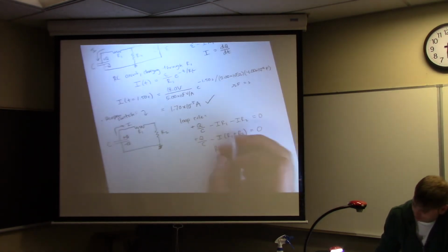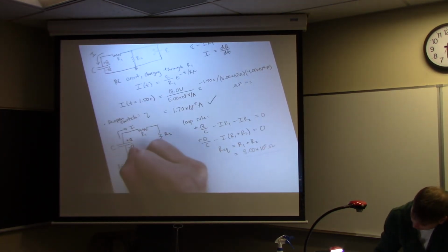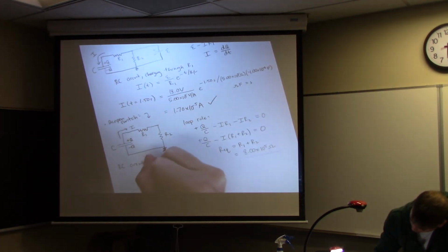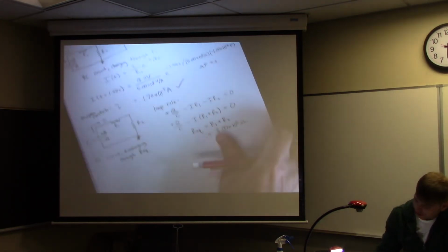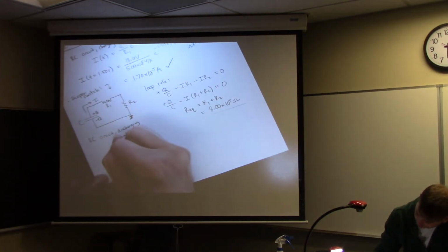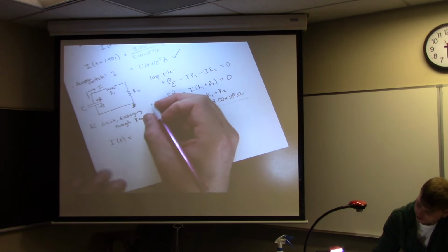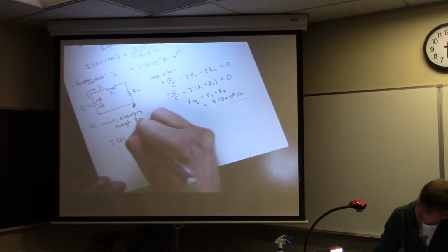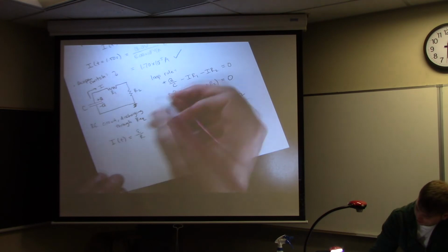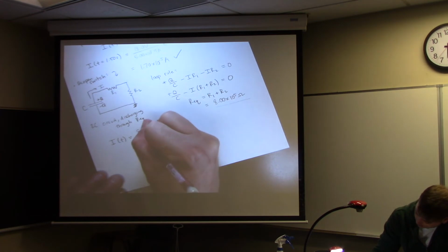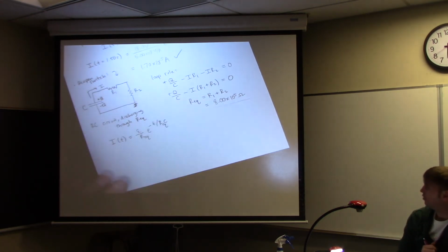Okay? So with that said, we have the RC circuit, and we're discharging through R_eq. So now let's think about what kind of current we have, or what's the formula for the current as a function of time. Well, same as before, epsilon over R, and then we have e to the minus t over RC. But now we know the R value we should be using is R_eq.